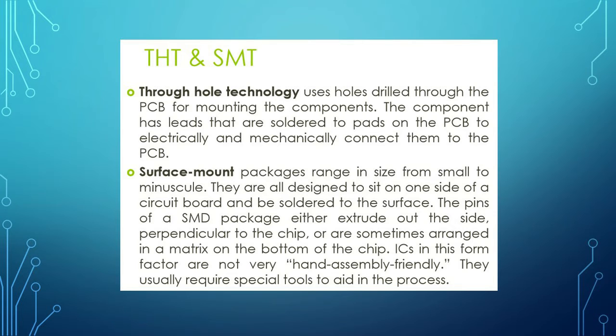THT is Through Hole technology, which uses holes drilled through the PCB for mounting the components. The component has leads that are soldered to pads on the PCB to electrically and mechanically connect them to the PCB.